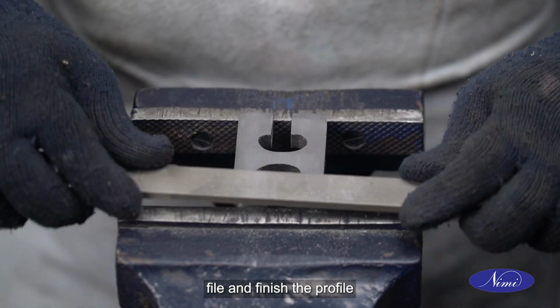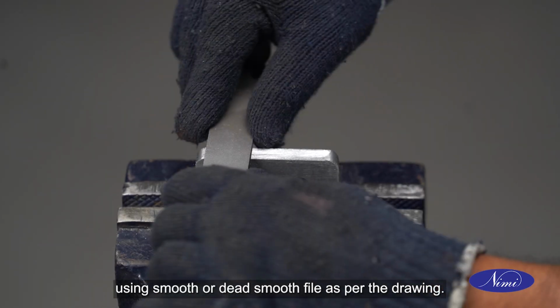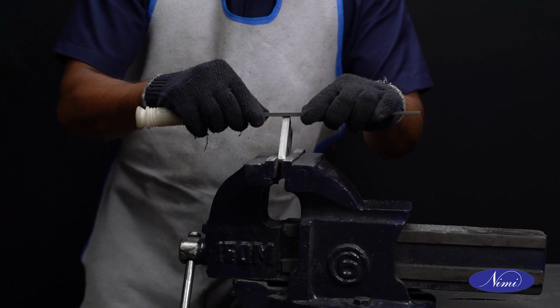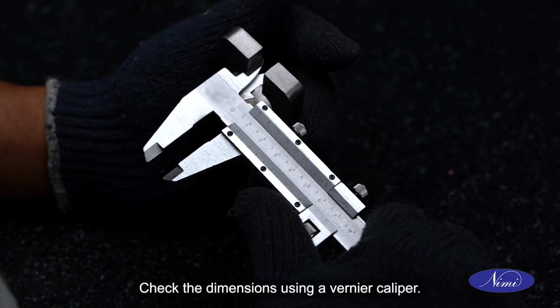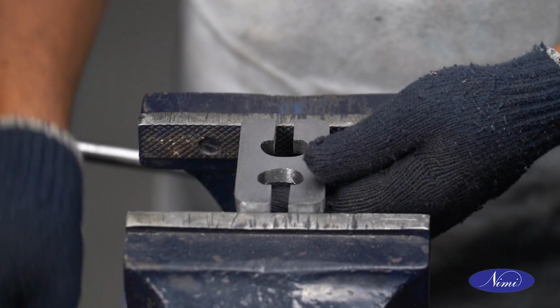File and finish the profile using smooth or dead smooth file as per the drawing. Check the dimensions using a vernier caliper. Finish surfaces and remove burrs.